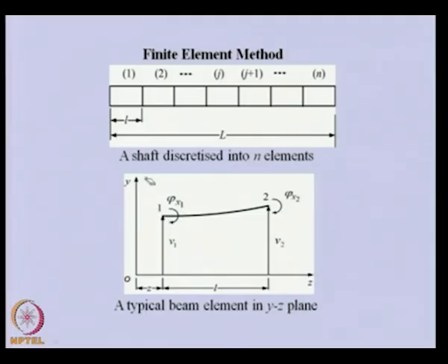As we discussed in the previous lecture, in a Euler-Bernoulli beam, the motion in a single plane is uncoupled with respect to the orthogonal plane motion. So, we can analyze the one plane motion separately, and the other plane motion orthogonal to this will be identical to that. That means the zx plane motion we can analyze on similar lines, because in this particular case element properties are the same in these two planes.